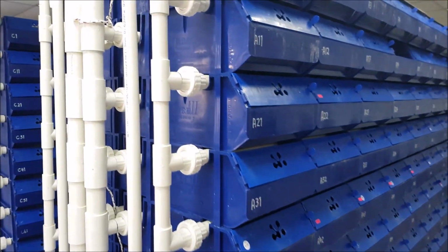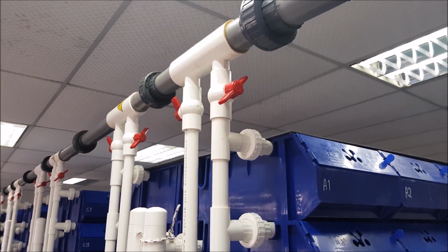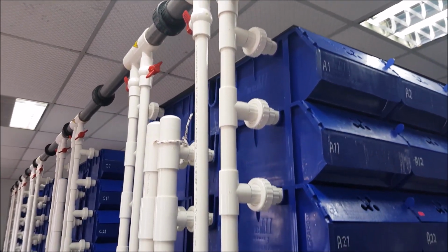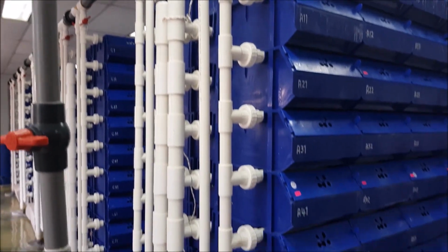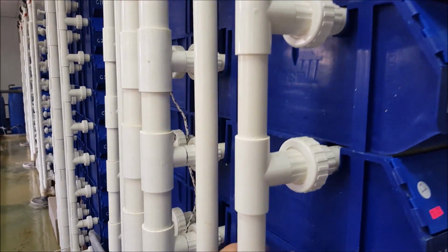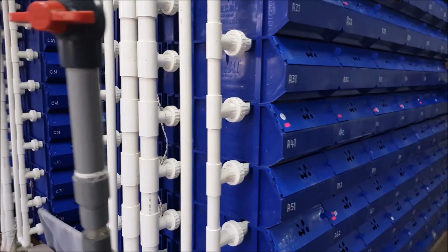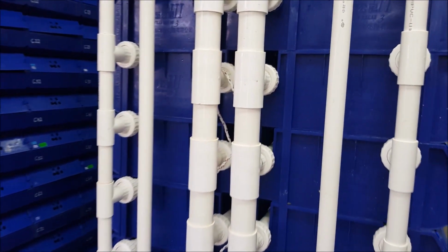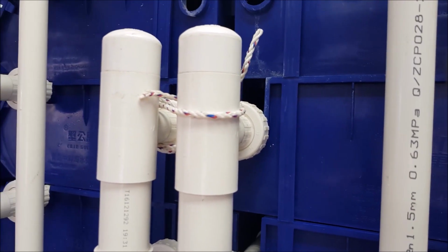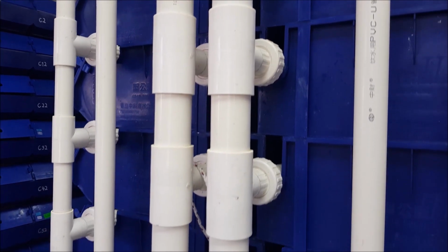I'm just going to show you where the water is actually coming from. This is the overhead piping in which treated water is being recirculated back into the boxes. The two pipes on the right that you see here are where the water is going into the box. It is being divided over here. On the fifth column, there is a valve inside that stops the flow from going into the box. Essentially, the pipe on the right controls the top 5 rows, and the pipe on the left controls the bottom 5 rows.